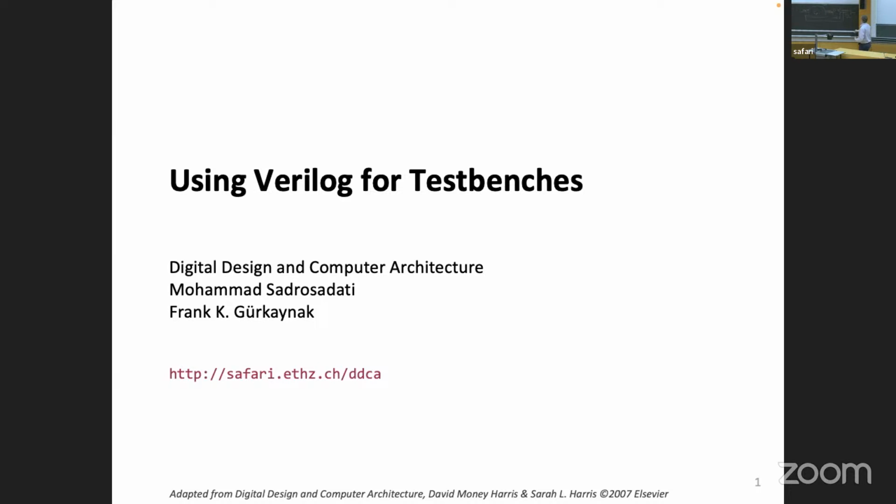We call these type of FSMs Moore. And there is a different version of them which takes the present state as well as the present inputs and generates an output, and we call those Mealy type of FSM. So this is what we were discussing. Good so far? Okay. Now when we look at this, this is the generic way of how we describe FSMs, but not all